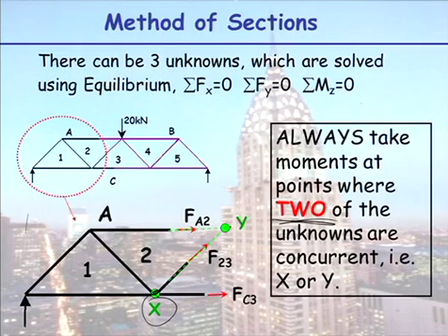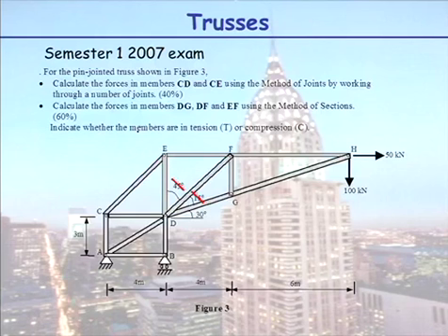So, as I've said from day one, you can take moments on the moon if you want. So don't think where you're taking moments has to actually be within your structure. In this point here, point y actually corresponds to this point up here. So the point where you take moments about can be outside of your structure. Okay, here's an example here.